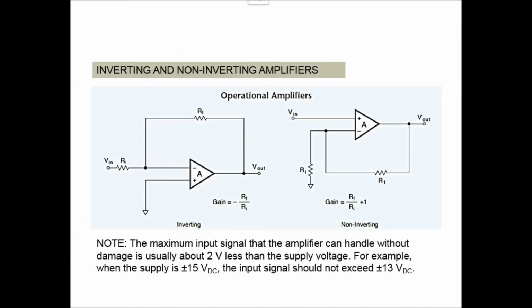The first thing you need to know is there is no current going into the op-amp, because we are considering that the input resistance of the op-amp is infinity. So for this branch, I is equivalent to 0. That's the first property. Similarly, there is no current into this branch as well.